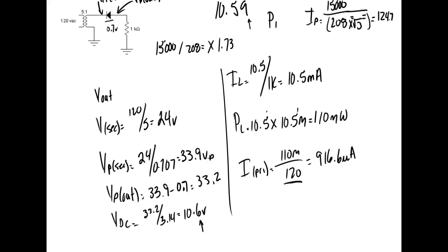So I'm going to say 208 times the square root of 3, 1.73, which is 360. So it's 15,000 divided by 360. And that's a common mistake. People don't get it right in their calculator. This is why your calculator has parentheses, right? You understand that? If you say 15,000 divided by 208 times 1.73, it's going to multiply your answer. And what's that? People just punch it in their calculator and they don't use those parentheses.